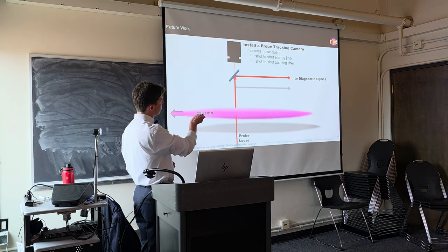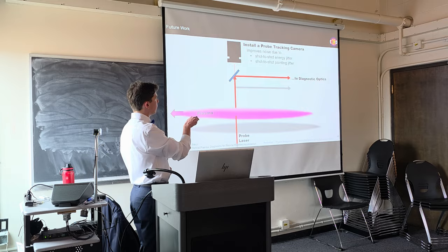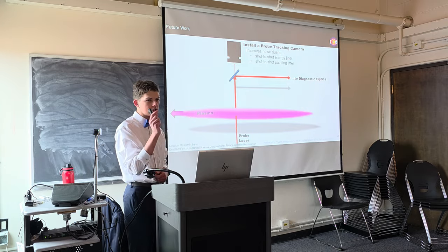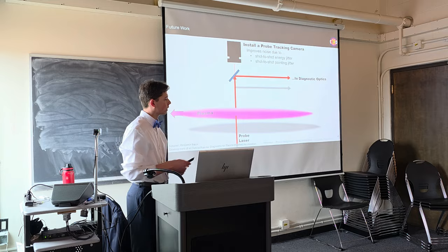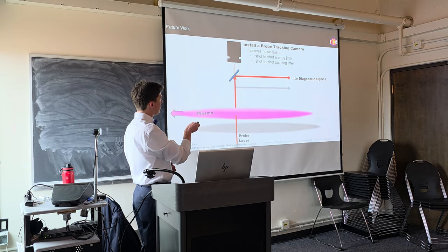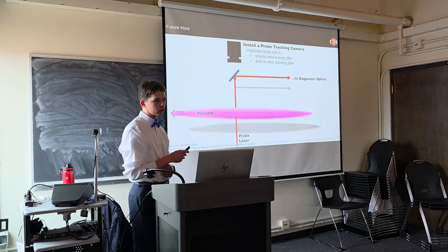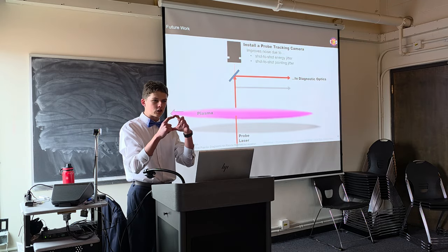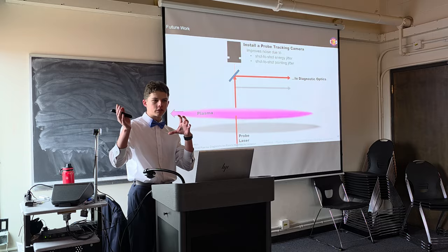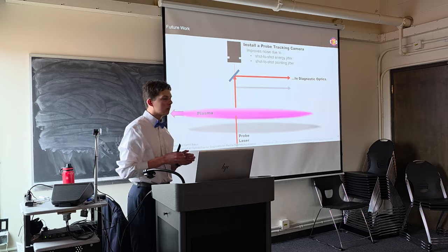And so there's also a method where for the energy, we could set up a photodiode here, just a high sensitivity photodiode. And there's a full electronic version where we could basically filter out the energy that we measure with the photodiode compared to the balanced photodiode, and then just get directly our change in phase measurement compared to some reference voltage or something like that, which makes the energy jitter even easier.